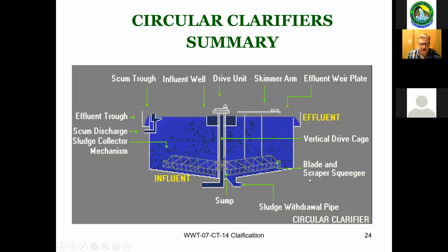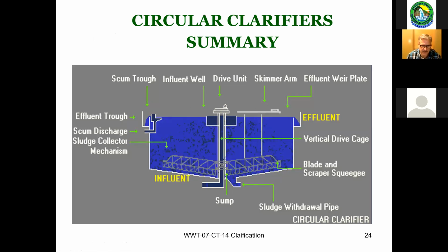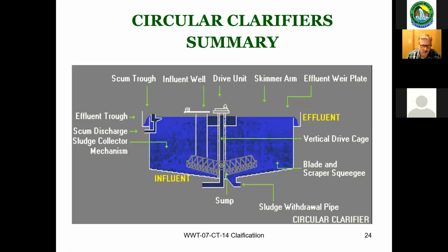Just a good graphic. I'm assuming the graphic's working on your end and you can see the mechanism turning around. So just review and make sure you understand the different zones of a clarifier and what's happening in those clarifiers. A little bit later this morning, we'll talk about typical maintenance and some of the things that can happen in a primary clarifier. I just wanted to go through the design and exactly what's happening in that clarifier.